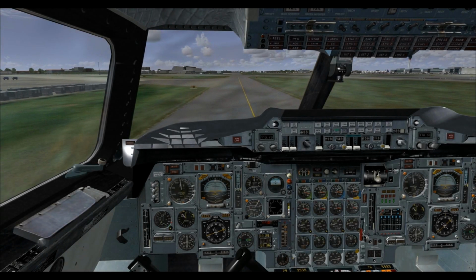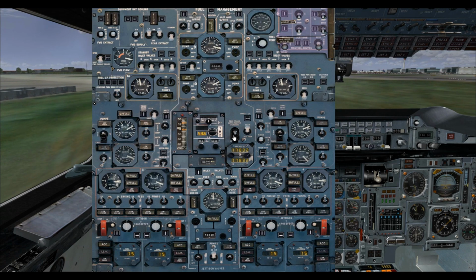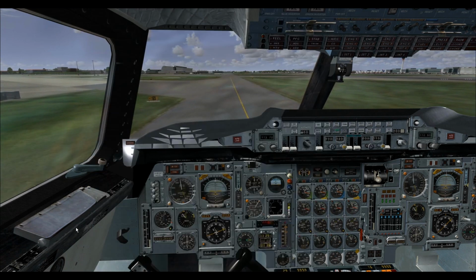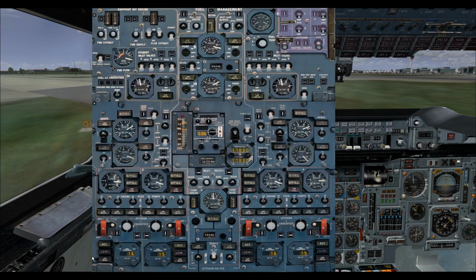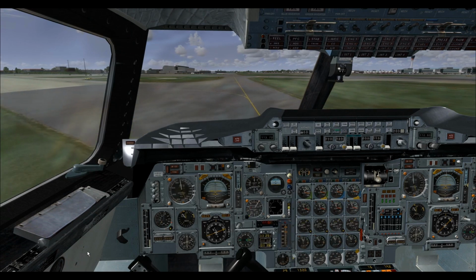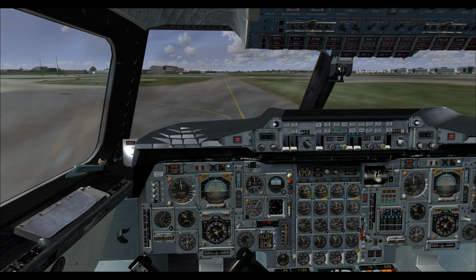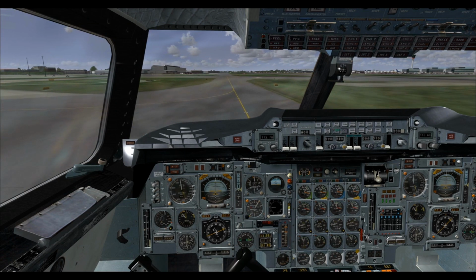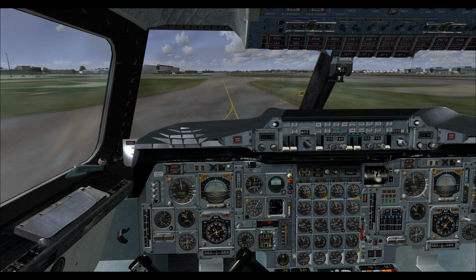Okay, so here's another scenario. You're taxiing along, and you've previously started your fuel transfer. Your fuel is moving backwards. You've set your load limit controller up to 10,500. You're going to pay attention to it, but you get distracted by talking to air traffic control or some other thing. And before you know it, your load limit controller has gone way past where you want it to go,